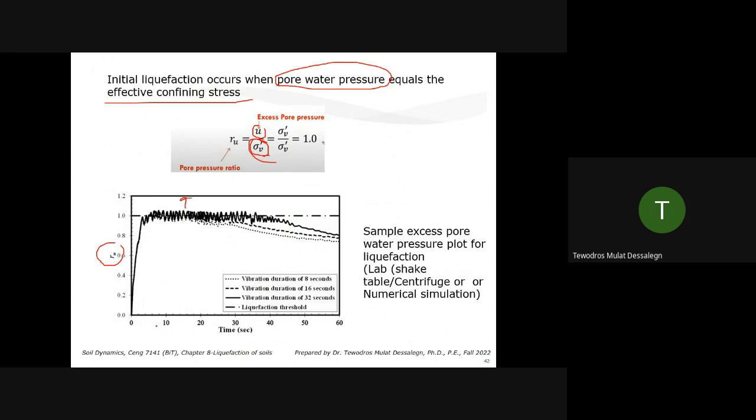So this can happen, let's say you have a time history of motion here. This liquefaction can happen, let's say, in the first 5 seconds. Pore water pressure was increasing. Then when it reaches 1 or around 1, it liquefies. This is what shows you liquefaction, the ratio of the pore water pressure to effective stress. Then in this area, it's in a liquefied state. After around 35 seconds during the earthquake, you see it going down. This is mainly because the earthquake shaking is also decreasing.